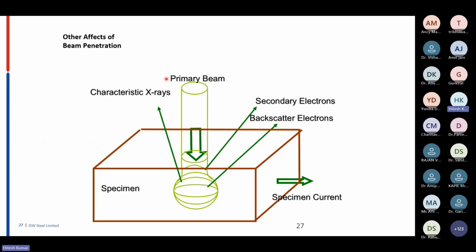All the electrons we are bombarding are taken up within the sample itself, so there will be no emission of electrons. Then you are not going to get any information. For that, you need to make your sample conductive, and you can use different types of coatings.